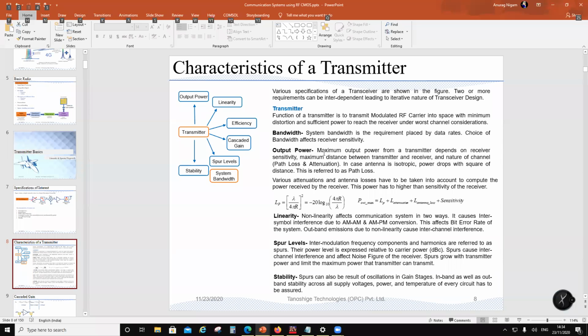And then I have two bandwidths I am concerned about. One is the system bandwidth, the other is the channel bandwidth. With channel bandwidth, I'm concerned about the noise, signal to noise ratio and all that. With system bandwidth, I'm worried about the interchannel interference and about the channel capacity. So two bandwidths come into the picture. If I design for a certain system bandwidth, the analysis for signal to noise ratio you will start with the channel bandwidth, not the system bandwidth. So bandwidth is one more concern.